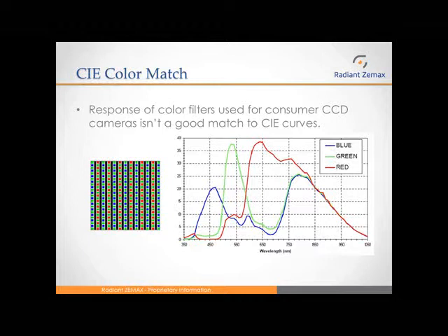And so our filter system does that quite well. For comparison, just for perspective, I have published here an example response for a consumer CCD. So like a point and shoot camera that you'd go buy at a store for $100 or something, uses a different type of technology. It actually uses a technology called the Bayer pattern, which means that gel is printed on this CCD as shown in this pattern on the left here.